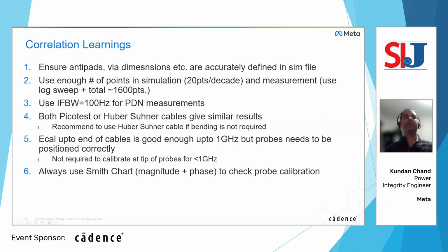So I already mentioned number 5, like we tried the eCal up to the end of the cables versus the calibration up to the tip of the probe. We're using short open load through calibration, but there was not much difference, at least for the frequencies we were interested in. So you could be using any of these methods, just make sure that the frequencies you're looking for are not too high.